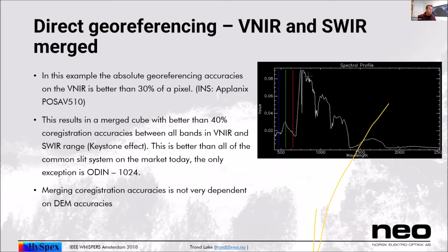So if you have two different cameras, then you have two optical axes, and you need to make sure that the supplier has full control of the boresights of each of them, and also how they are timed relative to each other. For example, our system is timed with, let's say, the frequency f with the VNIR and f divided by 2 on SWIR. So we have a GSD that's matched to that, which makes it easier to co-register afterwards.